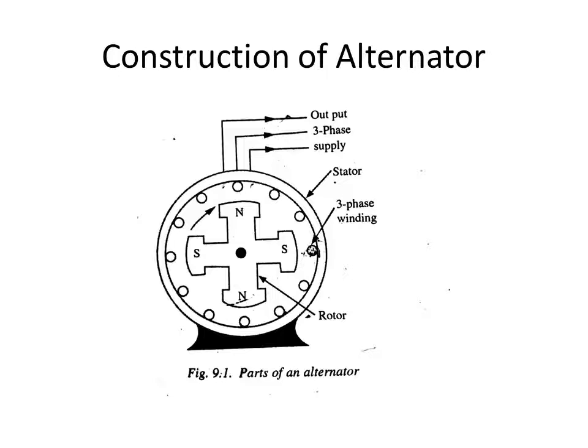The magnets also have field windings, which are conductors placed on the magnets. When an external DC supply is provided to the field winding, it excites the magnets. Because current flows through the field winding, which generates the magnetic field, the whole part becomes an electromagnet. Why are electromagnets required? We want a desired magnetic field, and a permanent magnet cannot give such a desired magnetic field.